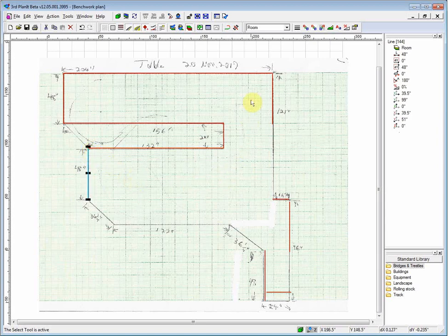Let's move to the upper right now. Using the Alt key to align, we'll get that line properly positioned and increase its length to 121 inches. Next, the 16-inch long line is aligned. This line is aligned and changed to 96 inches. Continuing around the bottom, we've made a lot of progress in this drawing.